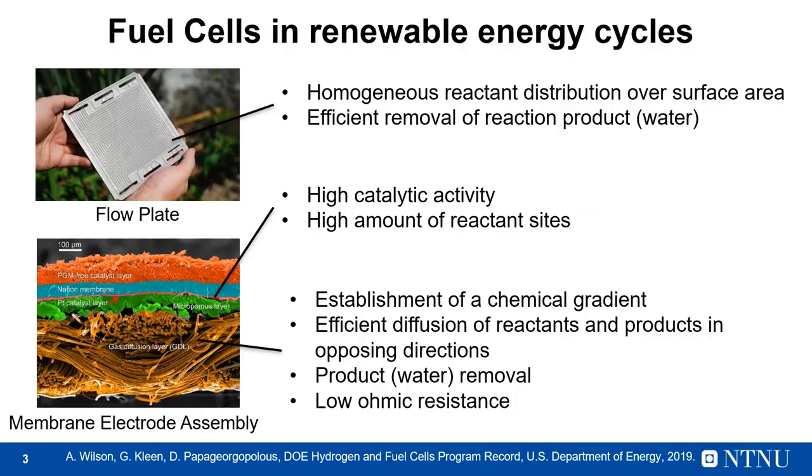Fuel cells. The fuel cell is built up by the bipolar plates, the gas diffusion layer, catalyst layer, and electrolyte. On the upper left here, we have the bipolar plate with machined flow channels. The bipolar plate needs to homogeneously distribute reactants over the whole surface area of the fuel cell and efficiently remove reaction product water. Here we can see the membrane electrode assembly,